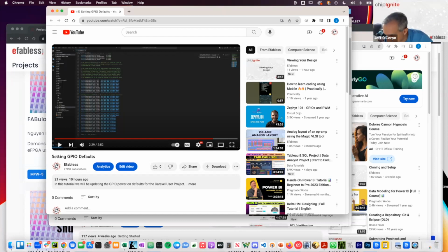Yep. Good. So next one, is it possible to connect the chip to a high capacity RAM chip? You could put an external RAM on the board. Yes. And the challenge will be the IO connections between this chip and that chip. The other possibility is to use a chip connected through a serial interface and use that chip to interface to a large capacity RAM.